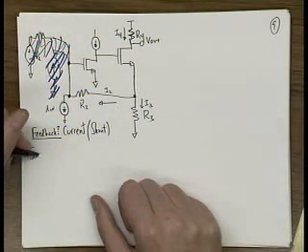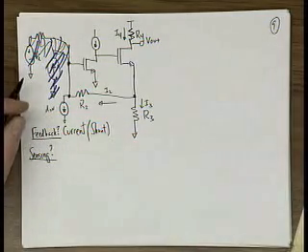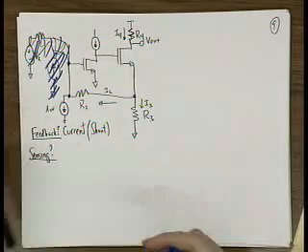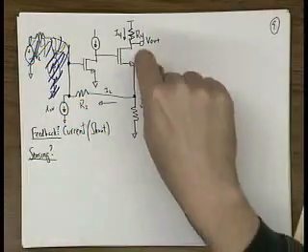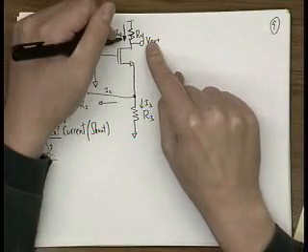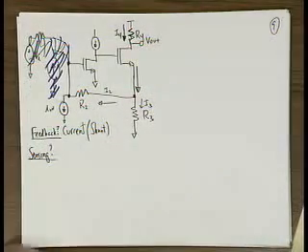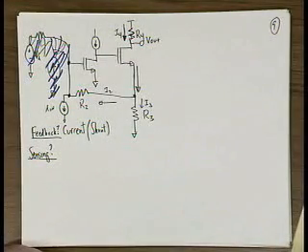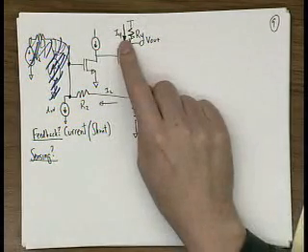So what are we sensing? Who thinks current? One person. Who thinks voltage? One person. Who thinks charge? We're actually sensing a current. Because even though this is where it's tricky. Even though the output is V out, what you can see is whatever current flows to make V out, I4, comes directly out, and that's what's being manipulated and sent back. Okay? We're basically sensing I4.